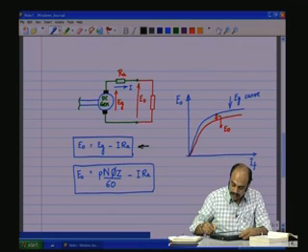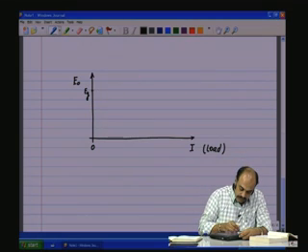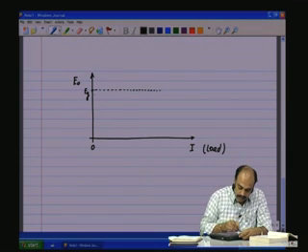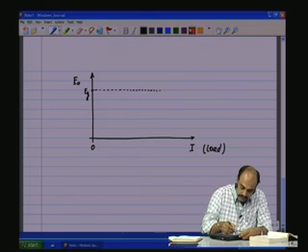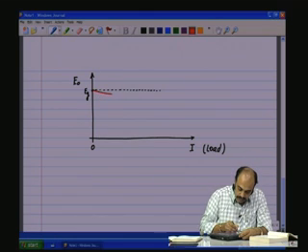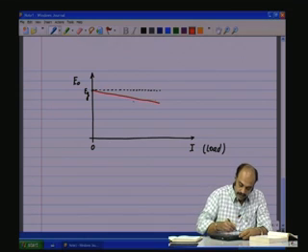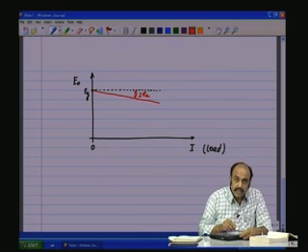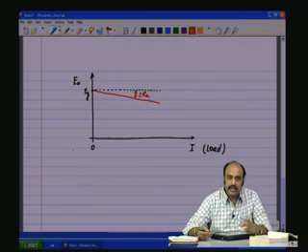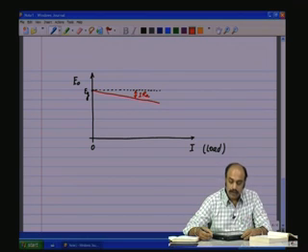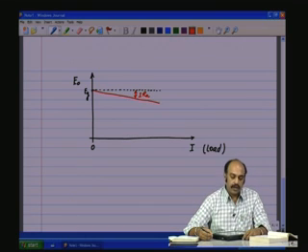And then as the load increases, so if this were Eg, let us say it is constant by some means, and as the load increases, E naught starts dipping, and that dip is the I into RA drop. So, it is not constant with different loads. What comes at the terminals of the generator is not constant with respect to the load, because of the non-ideality RA, there is an I RA drop.